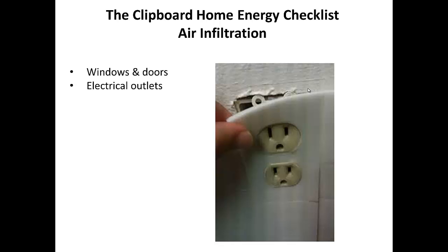Now here's an electrical outlet with a foam gasket. This is real simple, and you can get these at the hardware stores. There are electrical wires coming into the electrical box that's behind this sheetrock here. I'm sure if you haven't, try it this winter, but feel electrical outlets and see the air that's coming through. What this foam gasket does is help minimize the air that comes around and into the home through electrical outlets. When you put your cover plate on, it compresses around the edge and makes a good tight seal there. So this is a great little idea.